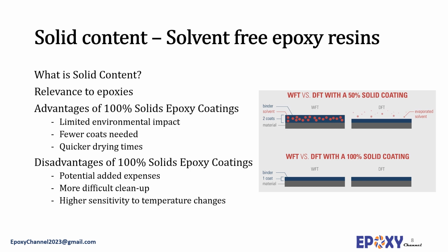100% epoxy systems are more difficult to clean up. In the event of overspray, low volatile content epoxy can be harder to clean. Finally, 100% epoxy resins show higher sensitivity to temperature changes. Environments where temperatures fluctuate could cause problems for these types of coatings.